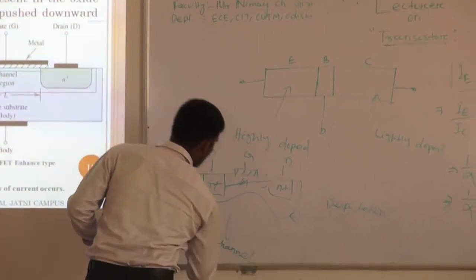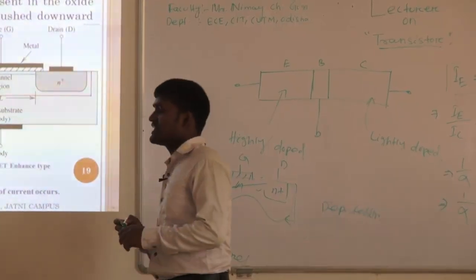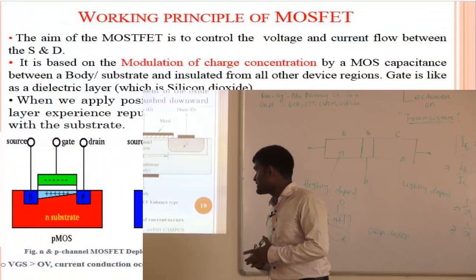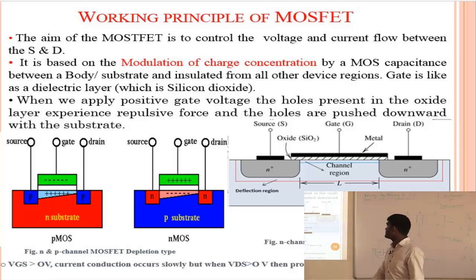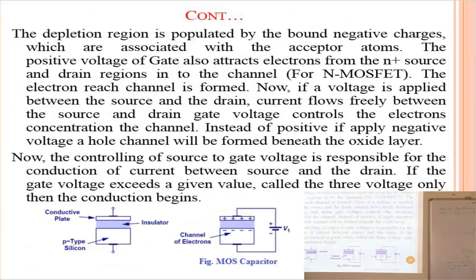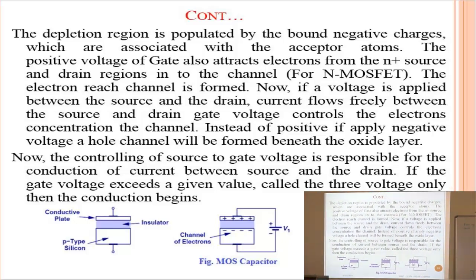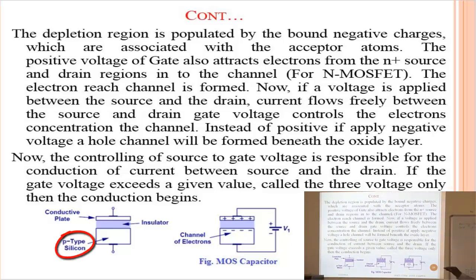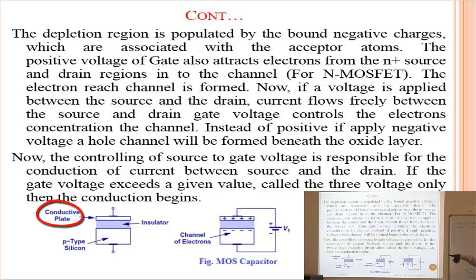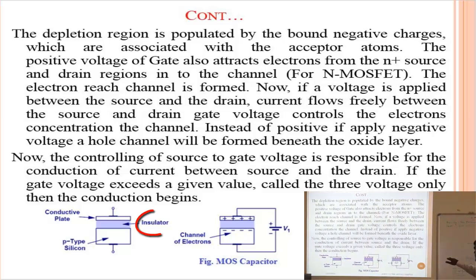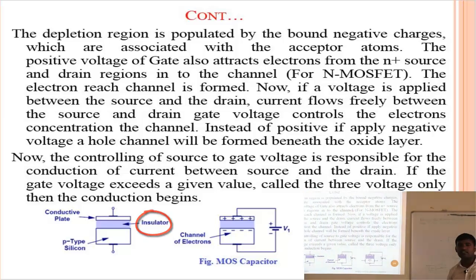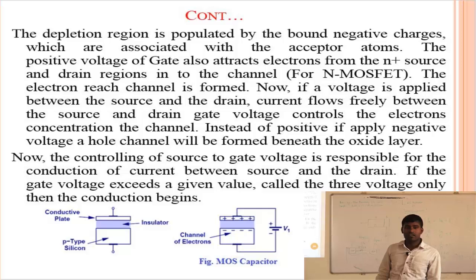Channel, where charge carriers pass through the channels. And next, how a MOSFET acts as a capacitor. You can see P-type silicon is there at the body part. P-type just acts as one electrode. In the upper part, a conductive plate is there. So two electrodes, or two plates, are there. In the middle section, insulator material is there. So it just acts as a capacitor.